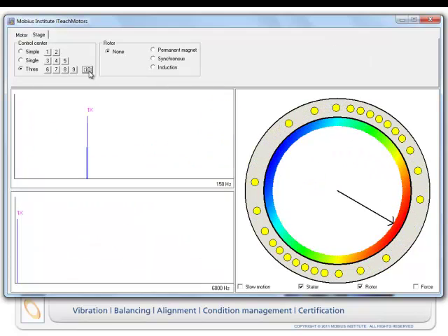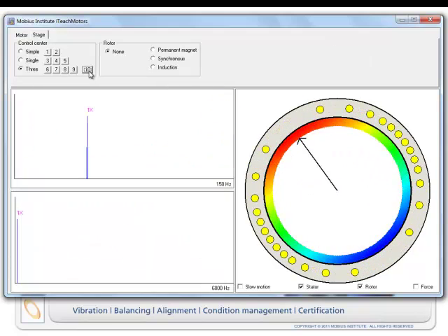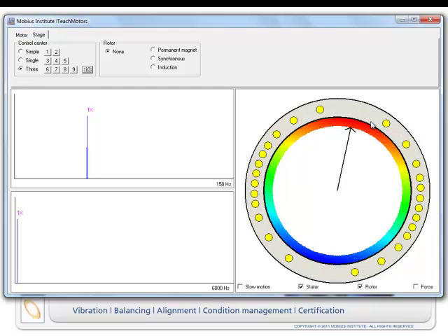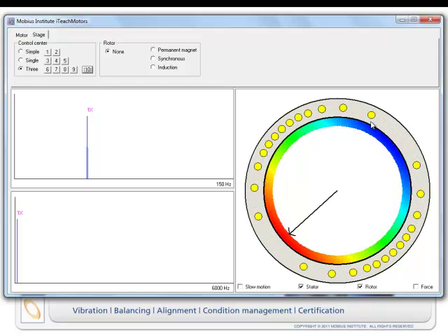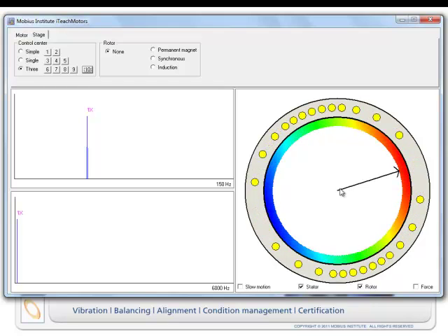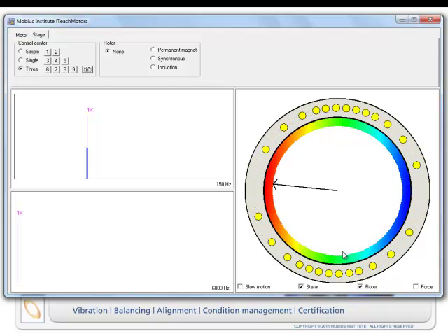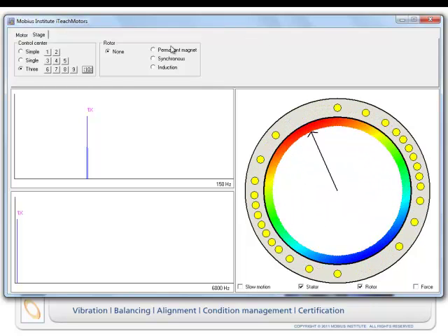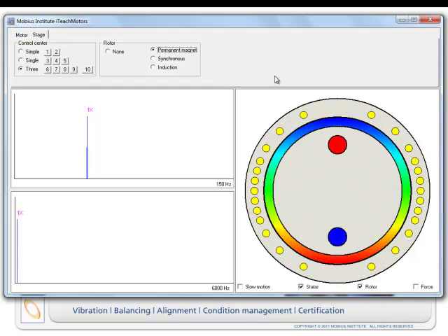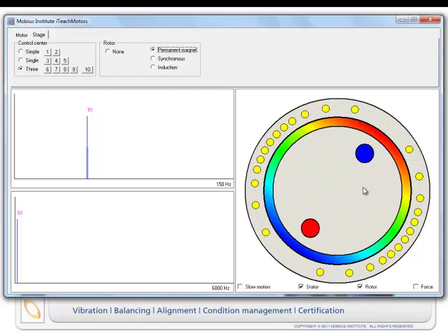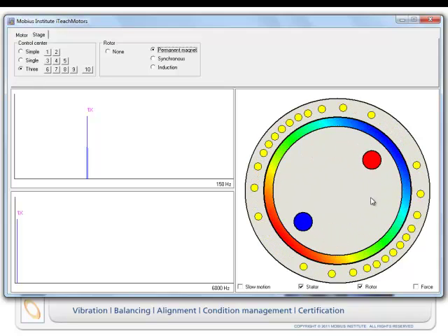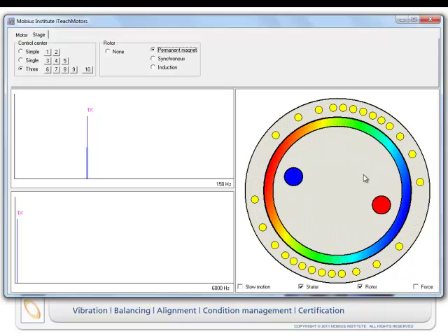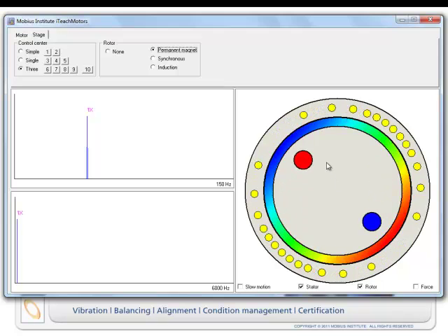So that's another way to view a motor, which is as a rotating magnetic field. It's almost like we literally have the stator spinning, creating a magnetic field. So we've got a strong north-south magnetic field rotating round and round the stator. So then we have to say, well, what are we going to do about that? What if we created a motor that had a permanent magnet? If the rotor was a permanent magnet, that permanent magnet rotor is going to chase that magnetic field around, and if it's not centered, there's issues and so on and so forth. But that's one way to do it.